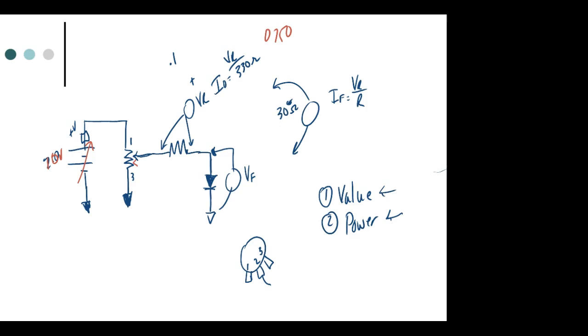So this is what we're going to have to do. Do y'all understand that? So set this to probably 10 volts. You're going to have to set it above what's required, right? You understand? So this is why, and that's in the book. Because you don't measure the resistors. We're not going to measure any values. What are we going to do? We're going to use the color-coded values. And if our calculations don't come up, that's what you need to start doing.